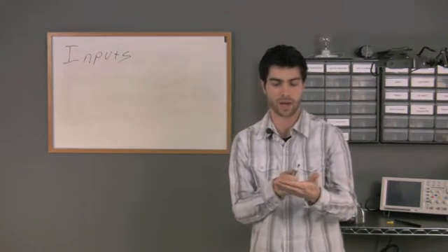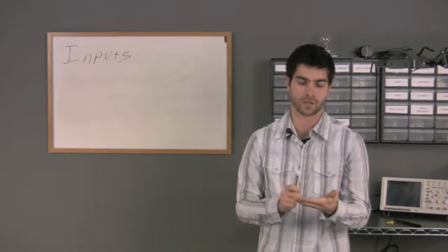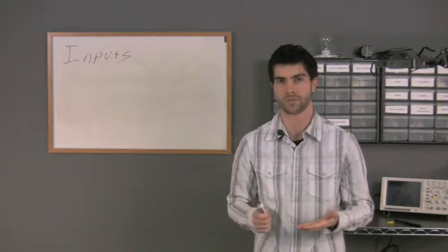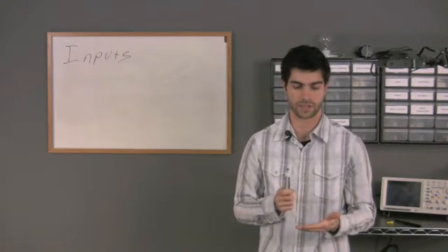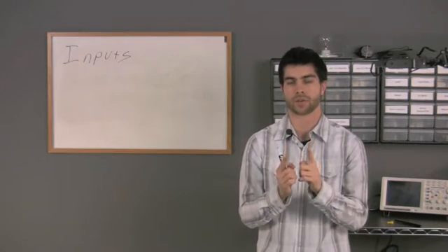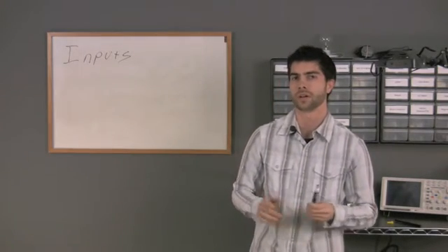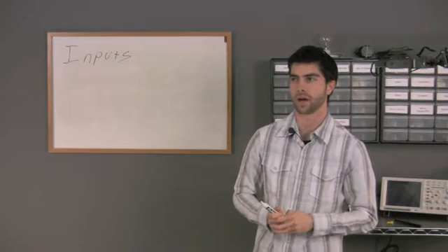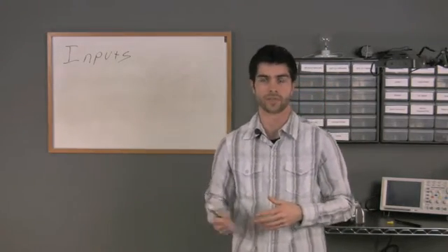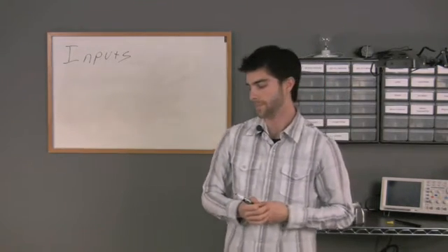So you can pick a spot on that scale where it's moving between and you can set a point there. And you can say, if it crosses this point, I want to trigger a relay or trigger an event. You can say, if it's within a boundary, I want to trigger a relay. There's a whole bunch of different things you can do there. We'll get into those more later on, how you actually use the inputs to trigger events and relays. We'll probably use the software and things like that to show you that.